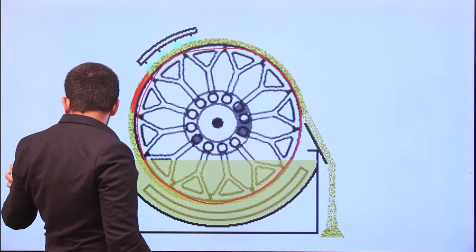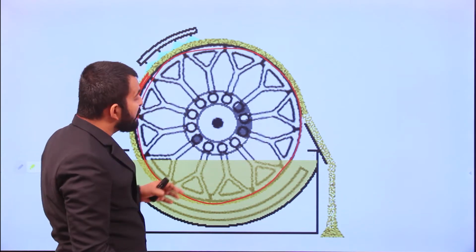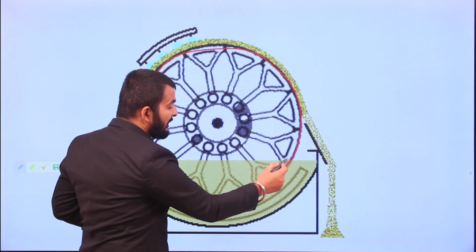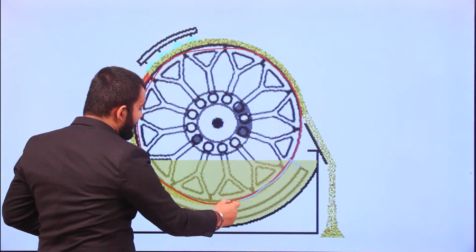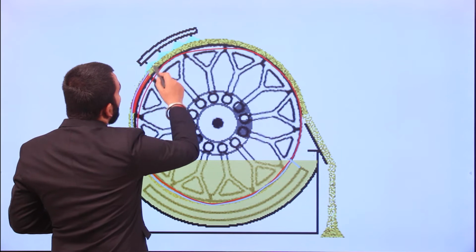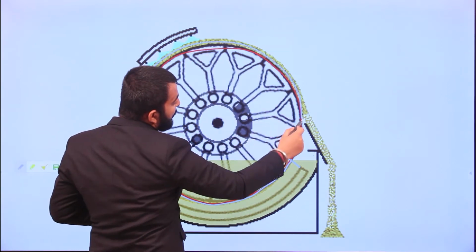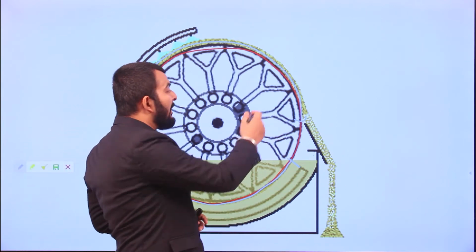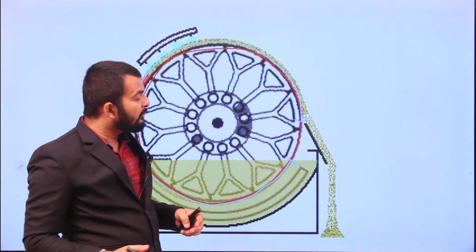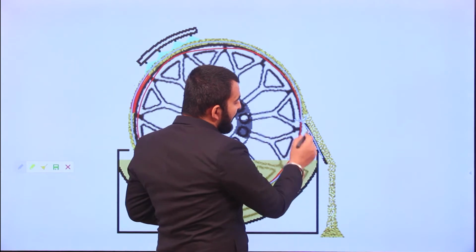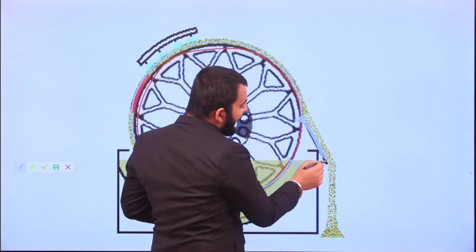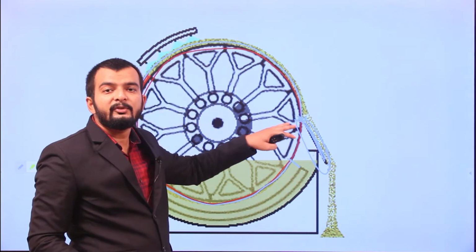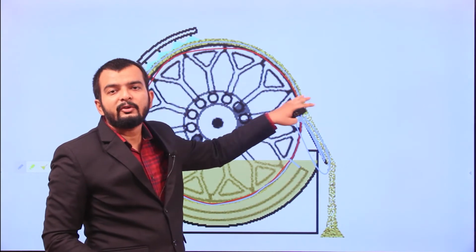So even before this drum has completed one full cycle, see, it is starting from here, the liquid that is coming in contact with the surface, before it completes one full rotation, up to 3/4 of rotation, your material will be almost dried. So you can scrape off this dried product or dried thin layer using a doctor's blade to scrape off all the material which has been stuck to the surface.